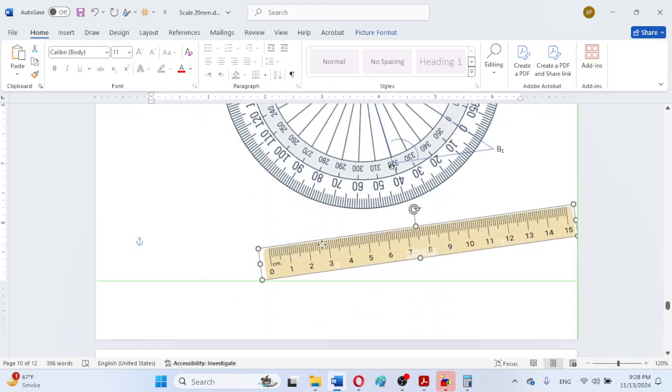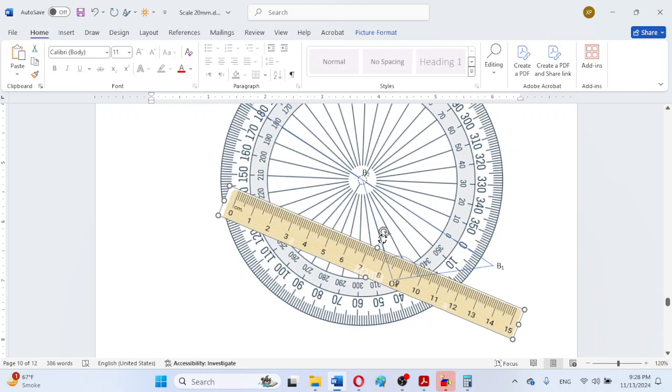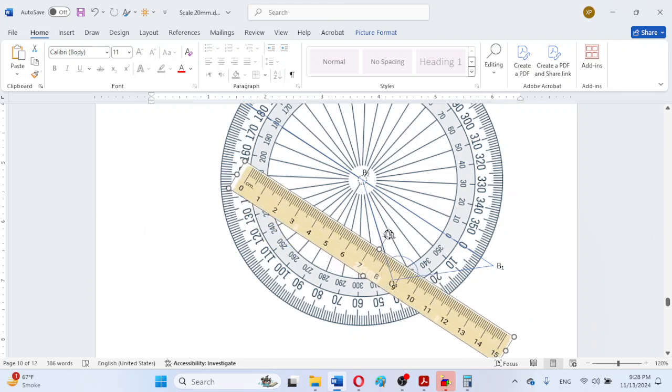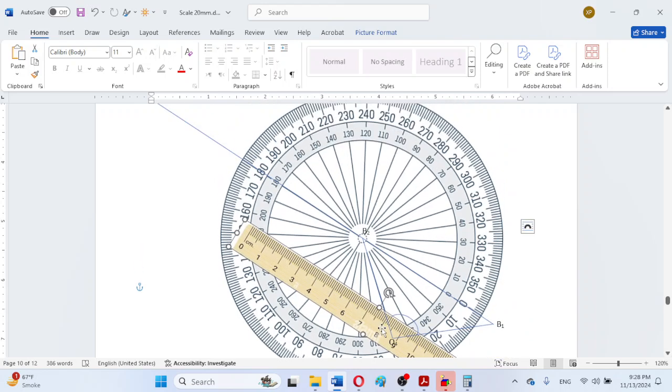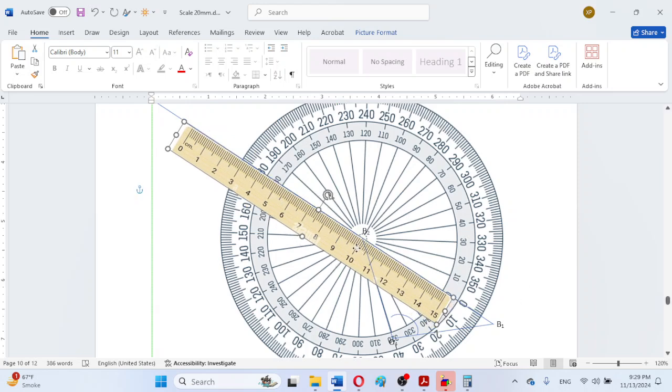Also we can place this scale to measure 10 centimeter. Remember that this is the assumed length of the connecting rod, and that may be changed if the Grashof law is not satisfied after that. So here we can observe that 10 centimeter will be here,